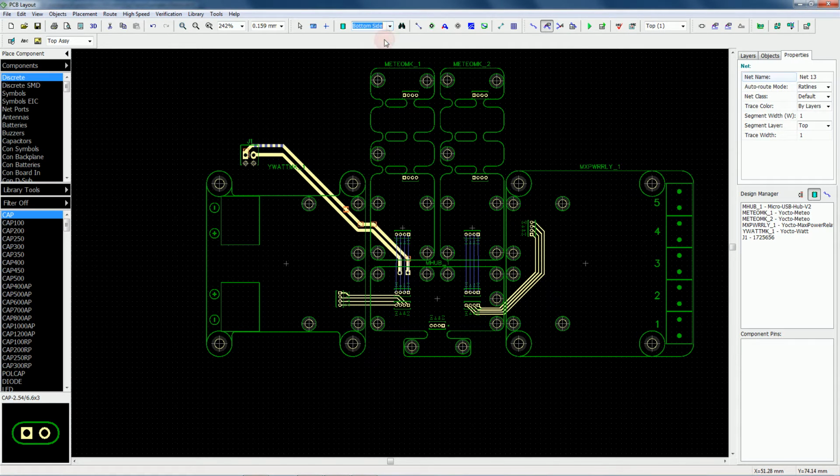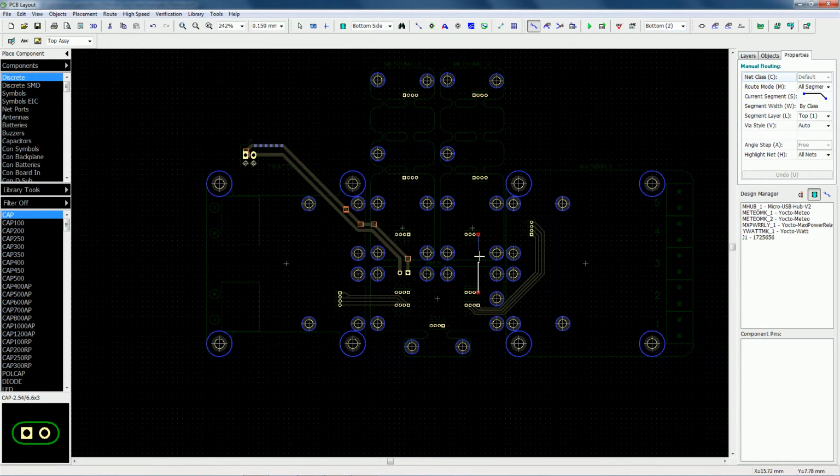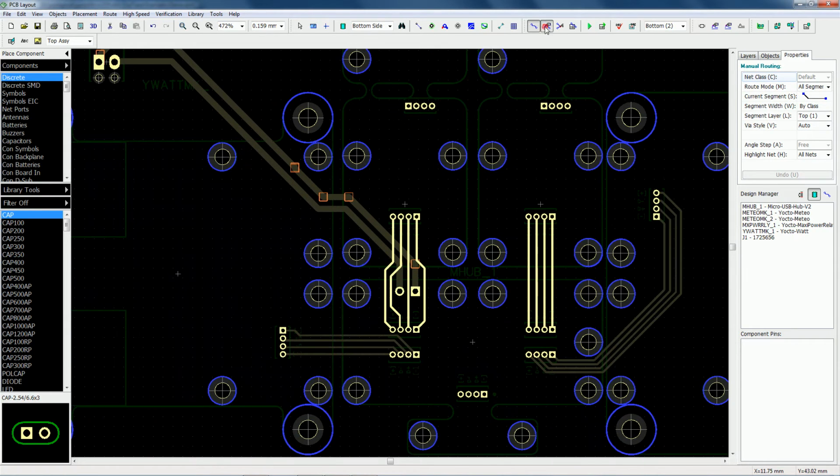It's best to use thicker tracks when you have more current going through them, like 1 amp or something like this. To connect the last 2 devices, I'm going to use the other side of the PCB, the bottom side. I can have tracks on both sides of the PCB, and this makes it much easier to do routing and avoid tracks that cross each other. So you see, in this case it's very simple. I can use a straight line. For the second one, I still have to go around the power socket pads, but it's still easier. I can have one track going between the two, and the other I just have to go around. I just have to figure out how to get my wires properly, and I'll fix them afterwards using the track edition.